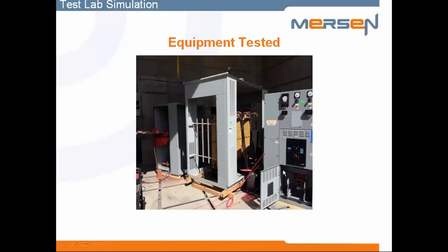And then the arc flashes were simulated over here in the low voltage switchgear. The 2 tests I'll be showing you were performed in this feeder breaker compartment. The main breaker trip unit was disabled to make sure that the primary side was the primary protection.